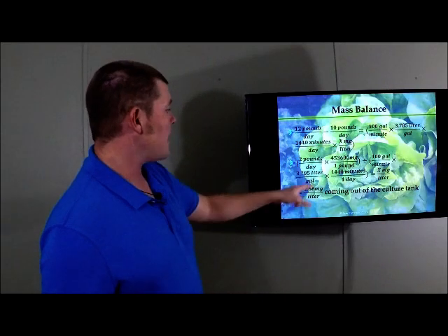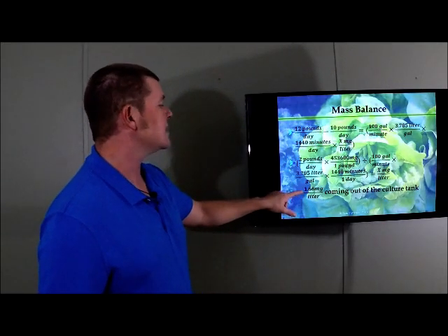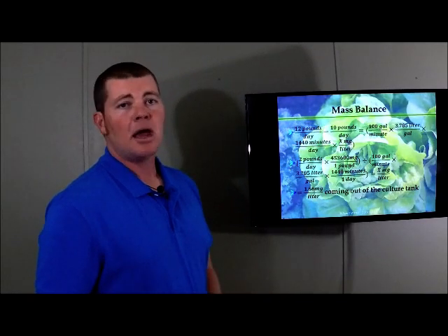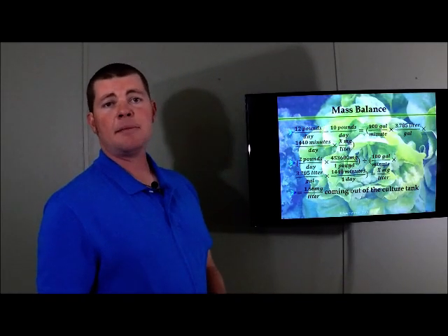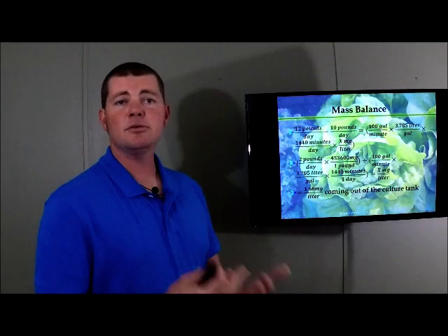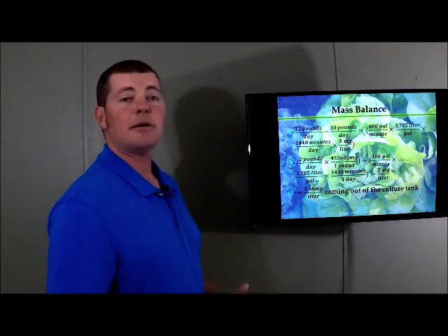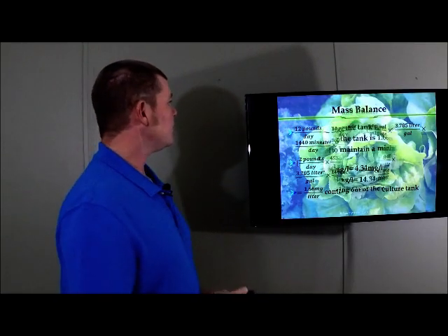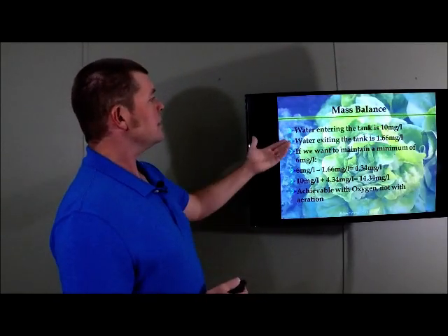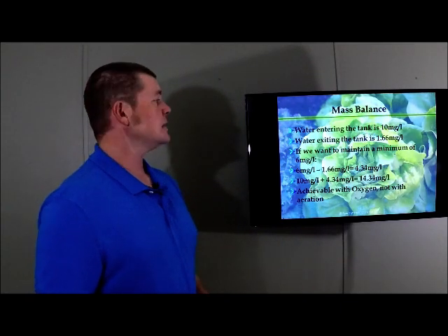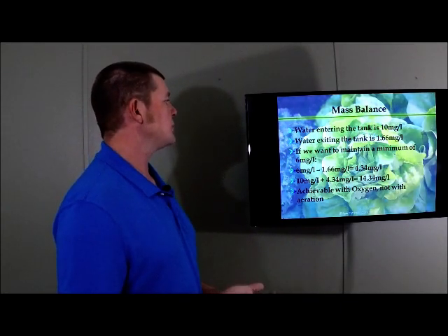Right here we do that math and we come out with 1.66 milligrams per liter coming out of the culture tank. And that's low. That means by the time the oxygen's in, the fish have used what they need and the water's leaving, it's extremely low. In fact, that's too low. So the water entering the tank is 10 milligrams per liter. The water exiting the tank is 1.66 milligrams per liter.